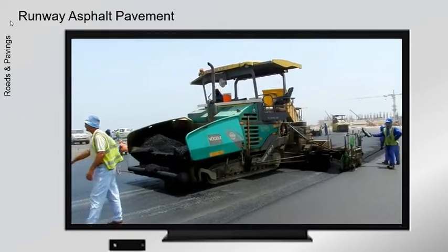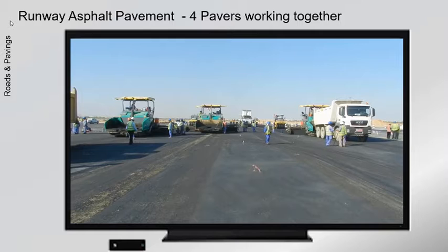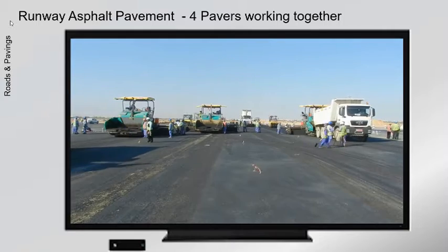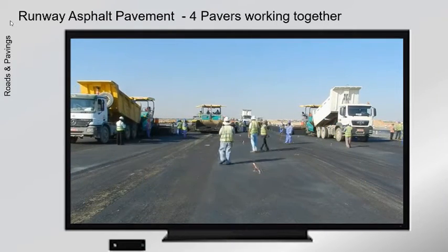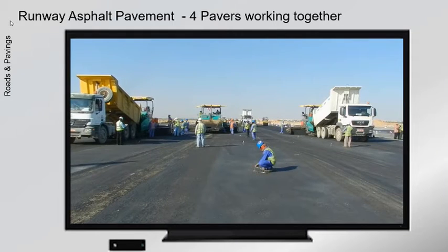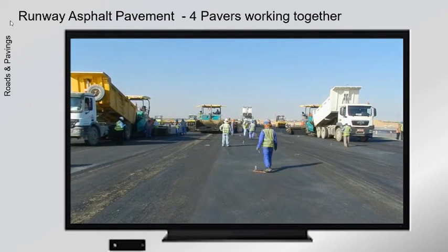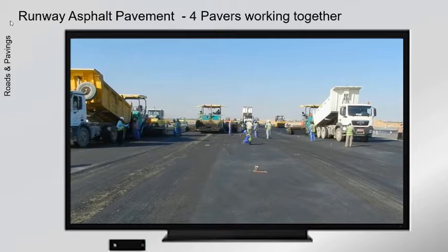The uncompacted asphalt level behind the paver is checked by pulling a string line between the longitudinal string lines at the 10-meter stringline pin locations and taking dip measurements using a tape measure. The asphalt after compaction reduces in thickness by approximately 20%.